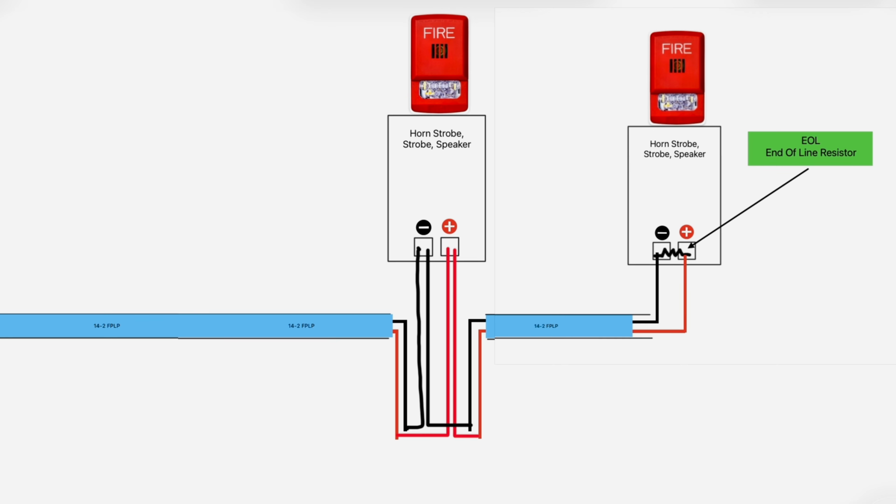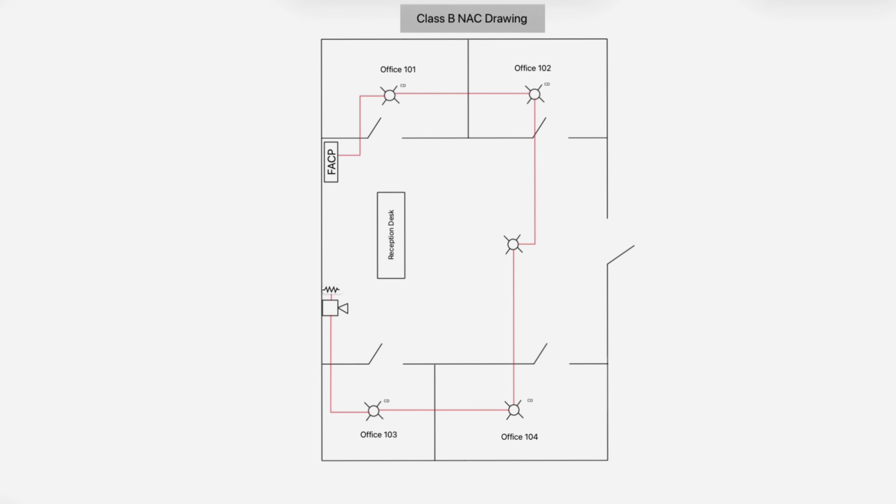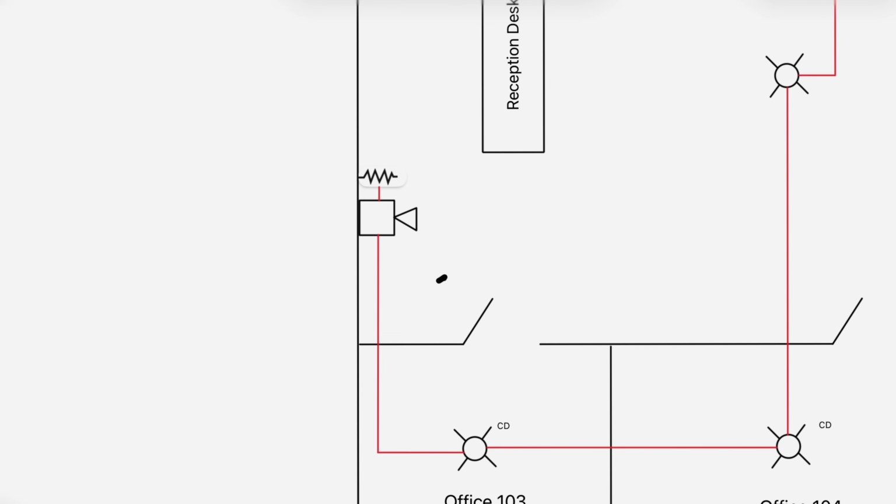It's important to not assume, at least in an ongoing project, that because there is only 1 cable in the box, that it is the end-of-line device on the circuit. Your drawings are always your best friend in determining this, which generally, on a set of drawings, looks like this. 1 incoming cable to the last NAC device, and a symbol for its end-of-line resistor.